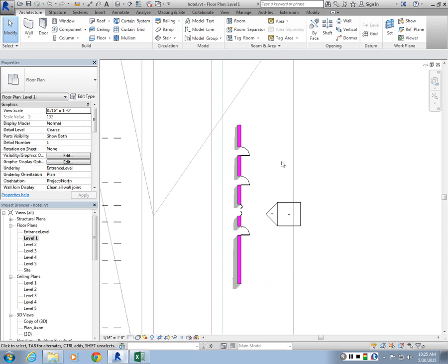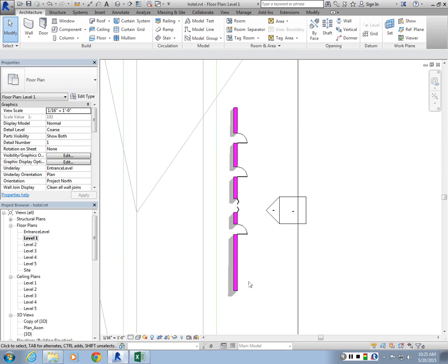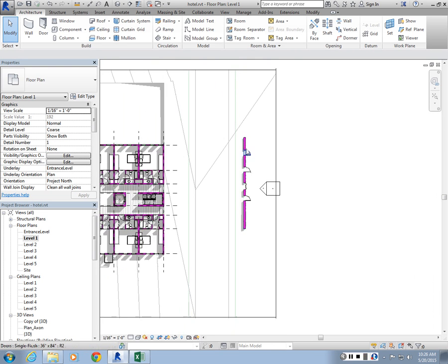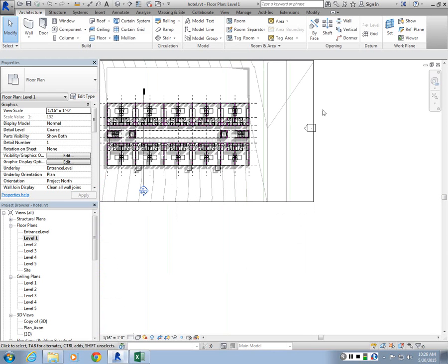I think this would make more sense when we create our own, and you will understand how this is structured, because you basically create a template for yourself, and then you store some basic variations of it, right? So you stretch it out a bit, call it like 3 feet unit. The other one you stretch in a bit, call it 2 feet, and then 1 foot. And when you load that family in the drop down, you will see them as variations, and you can iterate through them. But they will all be part of the same family that can generate those size variations. All right. So let's start looking at some of these in a custom family.